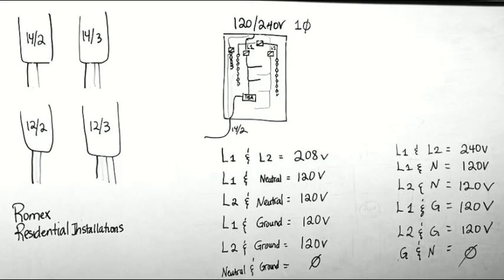Whenever we have a load, we need to know what load is going to be on that circuit. For example, on that receptacle over there, we have a microwave and a refrigerator. Both of those loads are on the same circuit. The microwave uses about 10 amps, and on the front of the refrigerator it says 600 watts. I know that both are connected to 120 volts because they're plugged into the receptacle, right? On one, I know the amperage being consumed and the voltage, but on the other, it only tells me 600 watts. So if you use Ohm's law, how many amps are being consumed by that refrigerator?